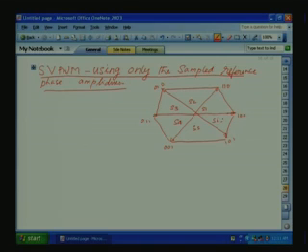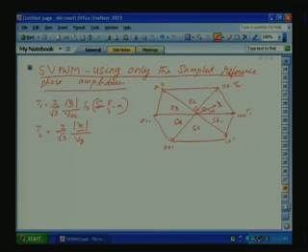In the previous class, we found for any sector, when the reference voltage space vector Vs is in any sector, and if the angle is measured from the start of the sector, the period T1 with which the start vector is switched, and T2, the end vector forming the triangular sector, and the 0 vector can be found from these equations. T1 is equal to 2 by root 3, this we have derived, times mod of Vs divided by VDC, times Ts, times sin of pi by 3 minus alpha. T2 is equal to 2 by root 3, Vs mod divided by VDC, times Ts, times sin alpha.